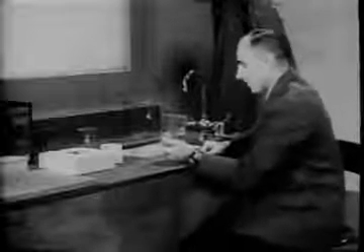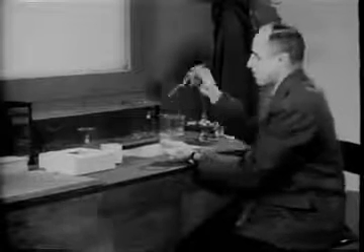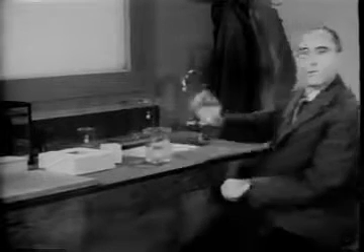The first concept is that of a continuous fluid. We know that matter is really made up of billions and trillions of molecules separated by empty space. But on a scale of size which is very large compared with molecular distance, matter appears to be continuous and unstructured. Rather than think of all the individual molecules of the real fluid, therefore, it is convenient to replace the real fluid by what we call a physical model. This model has neither molecules nor structure.